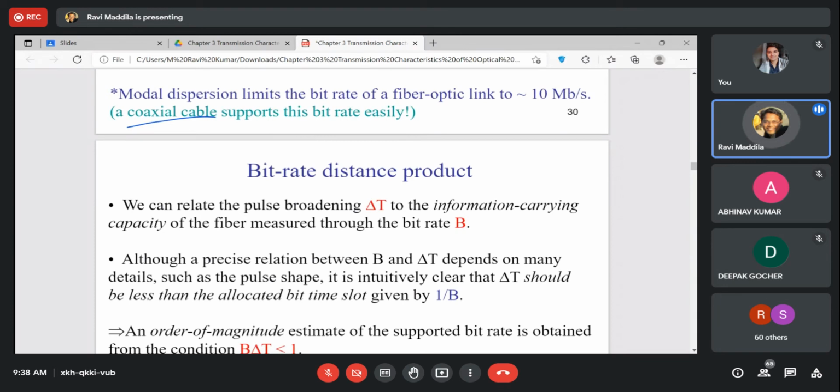If I consider 10 Mbps in an optical fiber with a multimode fiber, this would be limited to about maybe 1 or 2 kilometers. If I consider this over a coaxial cable, this also would be limited to about 1 or 2 kilometers. So the optical fiber as such does not have any major advantage. In that case, commercially, what is cheaper would be done. So a coaxial cable is cheaper, so a coaxial cable would be laid instead of an optical fiber.